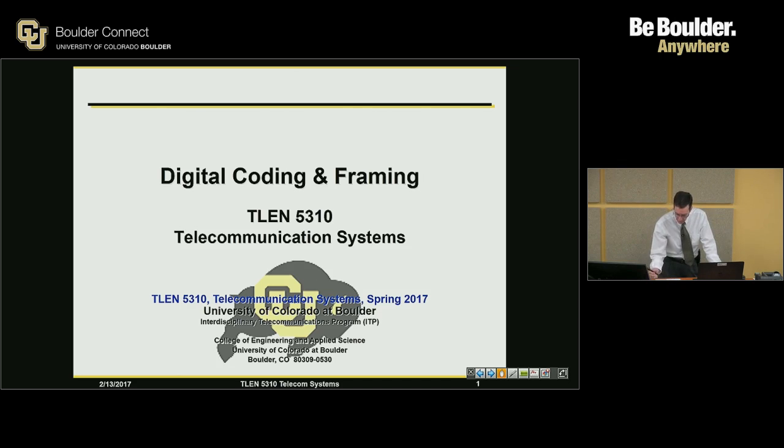Next one. Okay, we're talking about digital communications in Chapter 7, and there was a lot of information in Chapter 7. So, what are three advantages of digital communications? Superior performance in the presence of noise. You can reconstruct error-affected signals, so you can regenerate it, and it can support error correction. And were those the three that I picked?